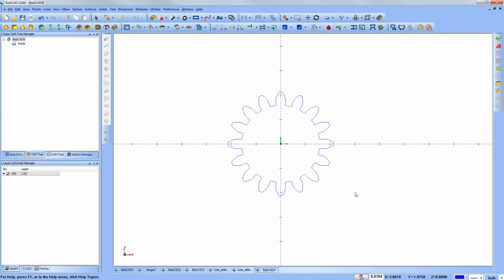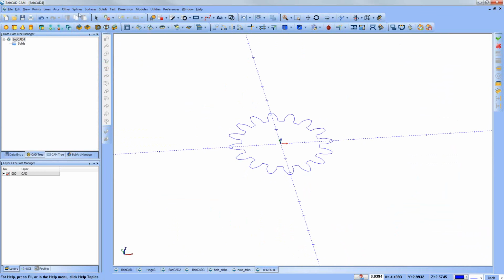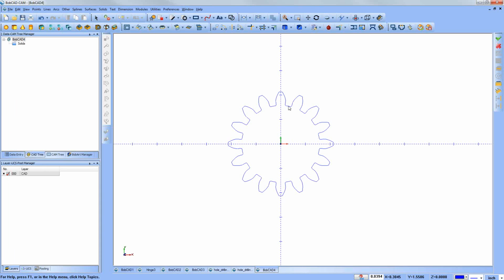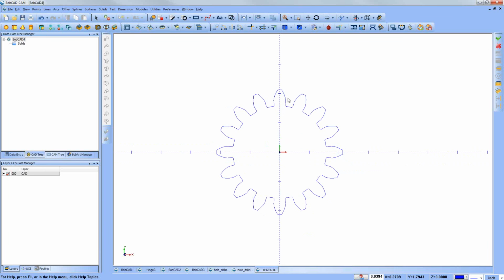The way you can do it is just set it up with a profile toolpath. I think it was creating gears that you wanted. The gear wizard allows you to put in values for that. If you want to create something separately, what you can do is, for instance, if I had this kind of profile, you can actually use the rotate command to copy and rotate how many instances you want around a specific diameter to create this gear.